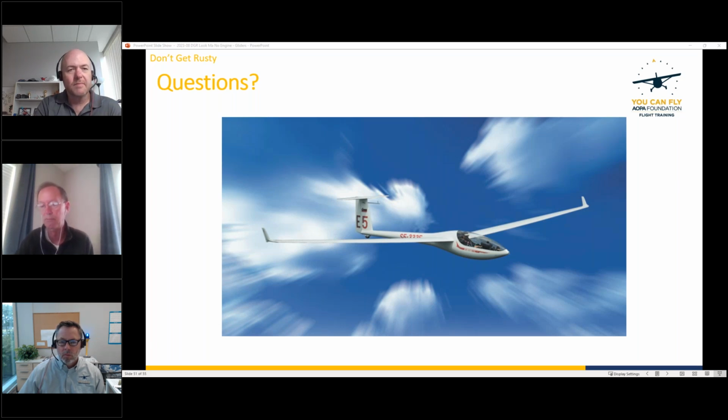Now there's a glider that Schweizer built called an SGS 2-32, which actually has a big back seat in it. It was designed to carry two people in the back seat. I had a friend of mine one time who wanted to go fly, and he was over the normal weight limit, but he was able to fly in the back seat of the 2-32 at considerably more than 240 pounds. Okay. So it is possible, but that's about the limit for most. And again, it's a certification limit.